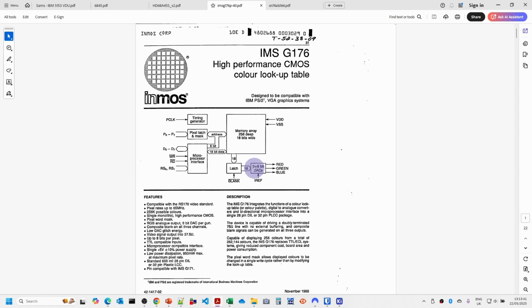So this allows us to have up to 6 bits for each colour. So this is what gives us a possible 262,000 colours, but we can only have 256 at a time. So this removes some of the complexities of working out resistor values and things to produce the voltages coming out of here, and means that we can actually program the colours in the video DAC registers here.